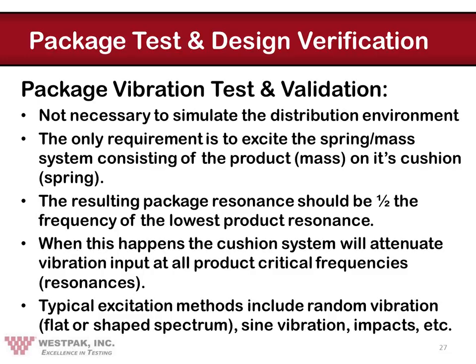Remember that it's not necessary to duplicate, or what's referred to as simulate, the distribution environment in the laboratory during this test. You really know what the environment is. We've already discovered that. What you're really concerned about is how does the cushion respond to the product, and in particular, does the cushion offer the impact and vibration protection when the product is most sensitive? If the answer is yes, then you really don't care what the distribution environment is like, because the package system will protect the product regardless of what comes along.